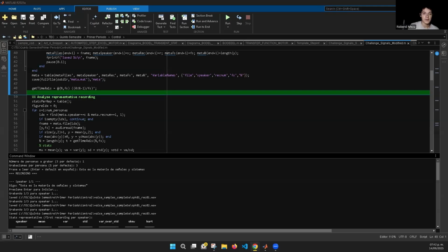The program will compute the frequency domain representation of the voice using FFT and PSD, with the FFT showing the raw frequency content, while the PSD shows the frequency distribution. Finally, a 1NN classifier performs a leave-one-out test, generating accuracy metrics.